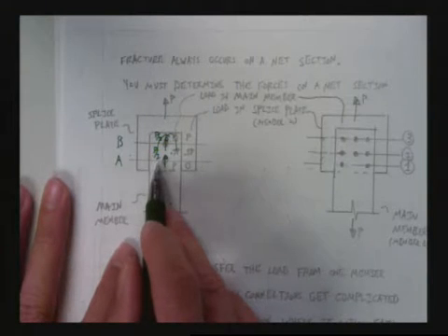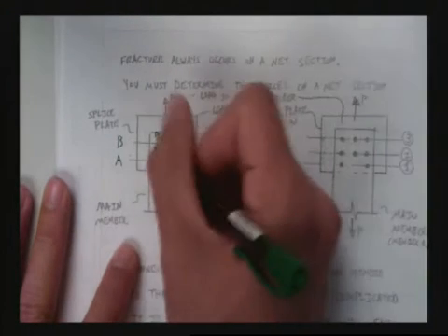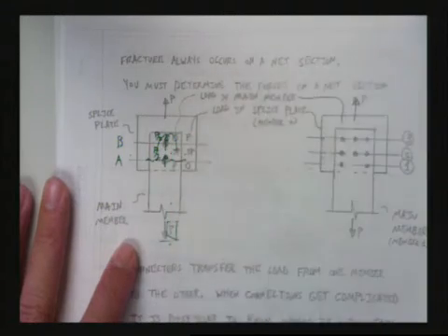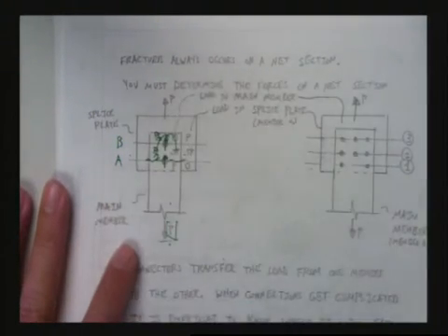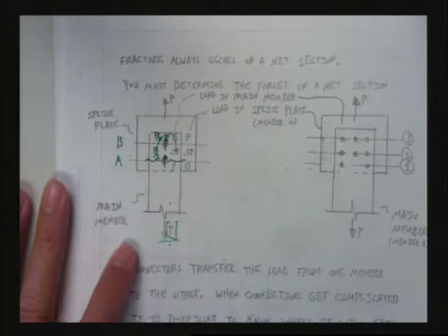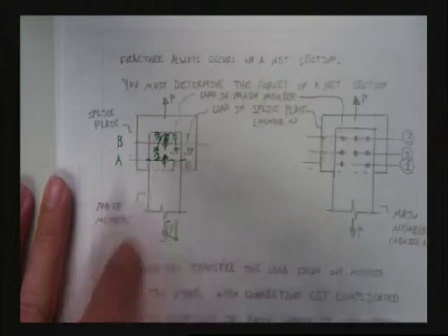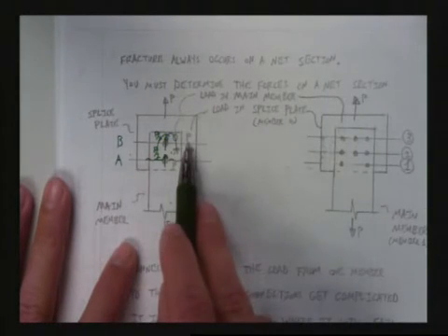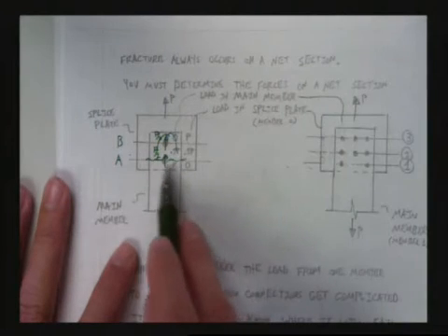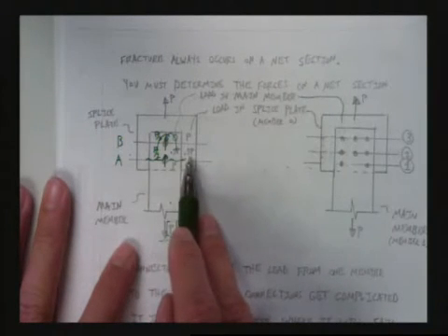So that's why we know it's always going to fail here. You with me? Now where's it going to fail on the bottom plate? Let's say we're checking the bottom plate. Where's it going to fail at? B or A? B. How'd you know? Because that's where all the load is. By the time you get to this line, you're only resisting 0.5 of P.